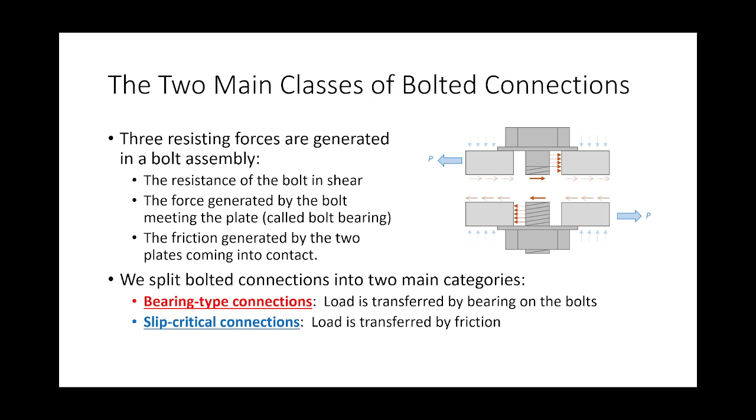So, for instance, as I tighten the bolt, the plates are going to squeeze together, right? Now, from a free body diagram and static standpoint, this is not an equilibrium because I'm missing stuff, right? There's going to be forces going this way pressing the plates together. I take a bolt, and I sandwich the plates together. The plates are in compression, and I didn't put that on there. And there's a reason I didn't put that on there, but you'll see this in a second.